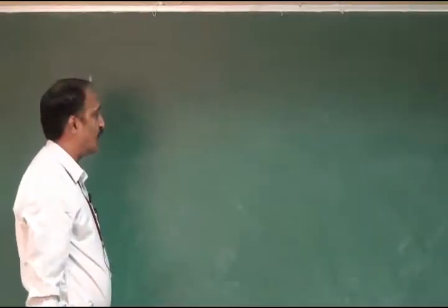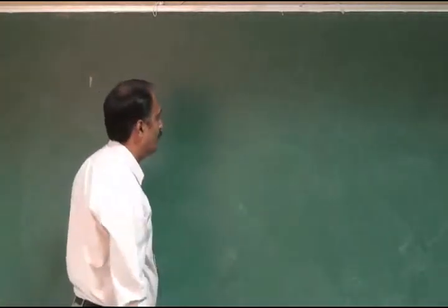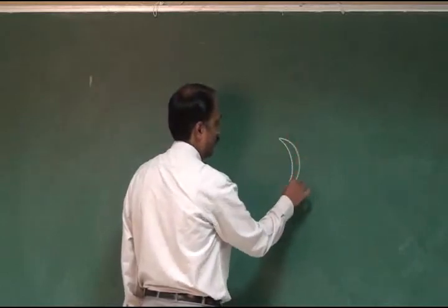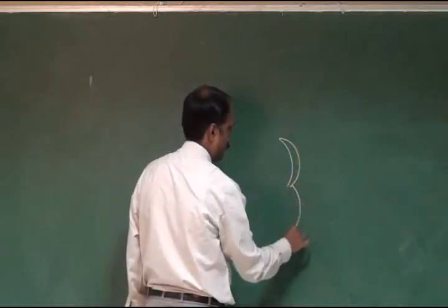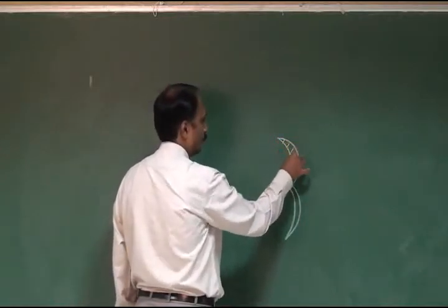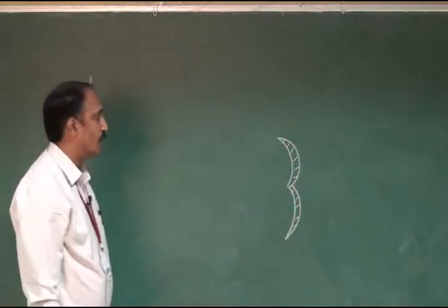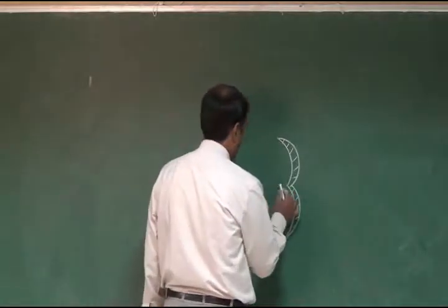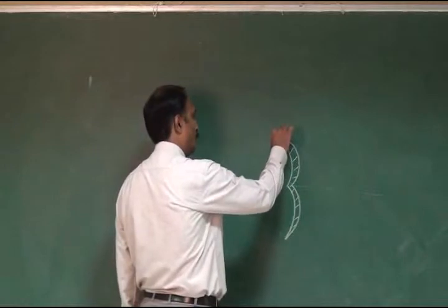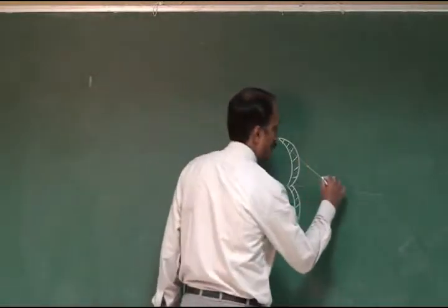Now we are going to construct the velocity triangles for Pelton turbine. For that we have to consider cross section of the bucket, like this. It's a cross section in top view. With respect to this central axis, this is the slope of the bucket at outlet, which is called the deflection angle.